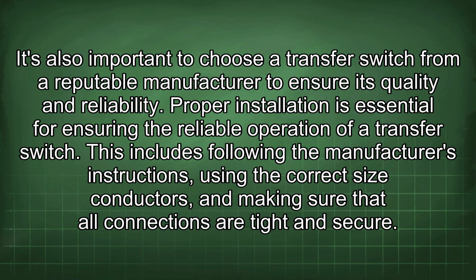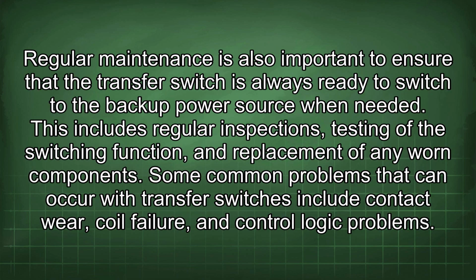Proper installation is essential for ensuring the reliable operation of a transfer switch. This includes following the manufacturer's instructions, using the correct size conductors, and making sure that all connections are tight and secure. Regular maintenance is also important to ensure that the transfer switch is always ready to switch to the backup power source when needed. This includes regular inspections, testing of the switching function, and replacement of any worn components.